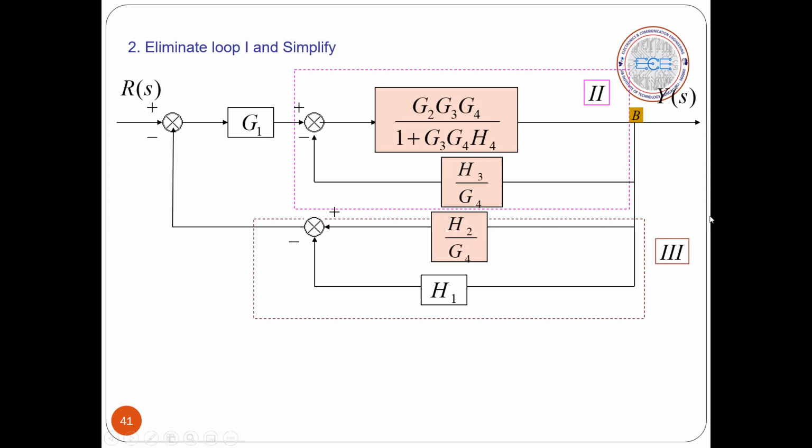And again here you have one loop. This is not a loop, you can see here, very sorry. This is one forward path, this is another forward path. So these two are forward paths here. One is plus, another one is minus. So this is plus and this is minus, you have to subtract these two blocks. Okay, whereas here it is a loop. Just come up here, it is a loop. So this negative loop you have to simplify, and these two are in parallel. So this and this you have to take the difference of.